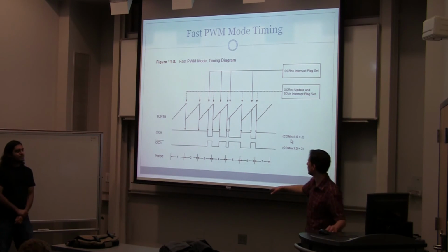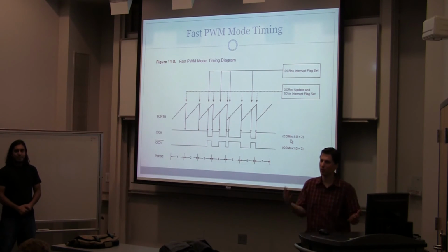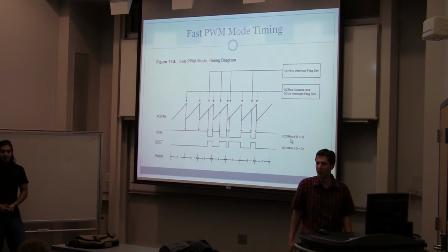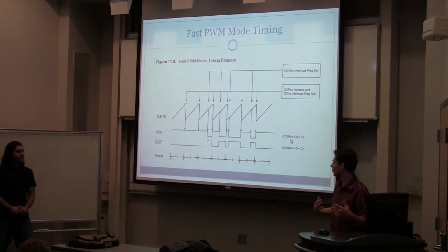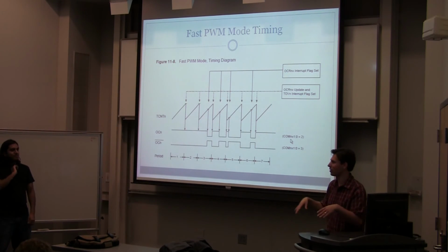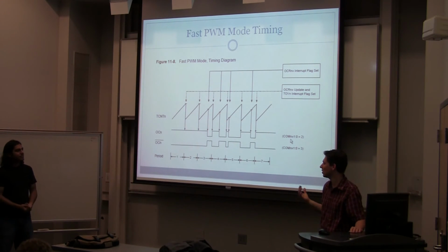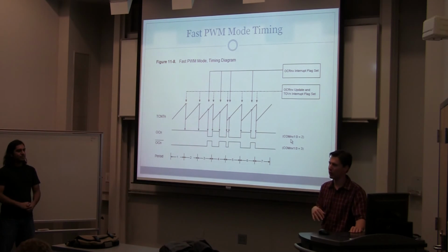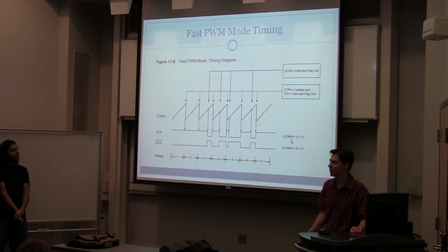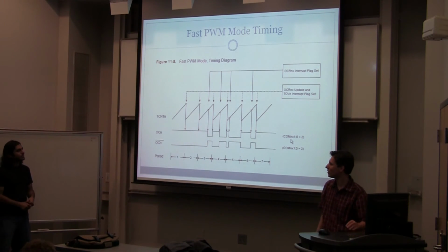If you're controlling a motor, this is happening at like 20 kilohertz, so this period is happening in, I guess, 50 microseconds. It's happening so fast that the motor essentially just sees it as an amount of power being put into it. It doesn't really notice that it's turning on and off that quickly. With an LED, we do it at about 100 hertz or 120 hertz because your eyes just can't detect anything that moves faster than that. Like those fluorescent bulbs are all going at 60 hertz, but we just don't notice. Most of them.